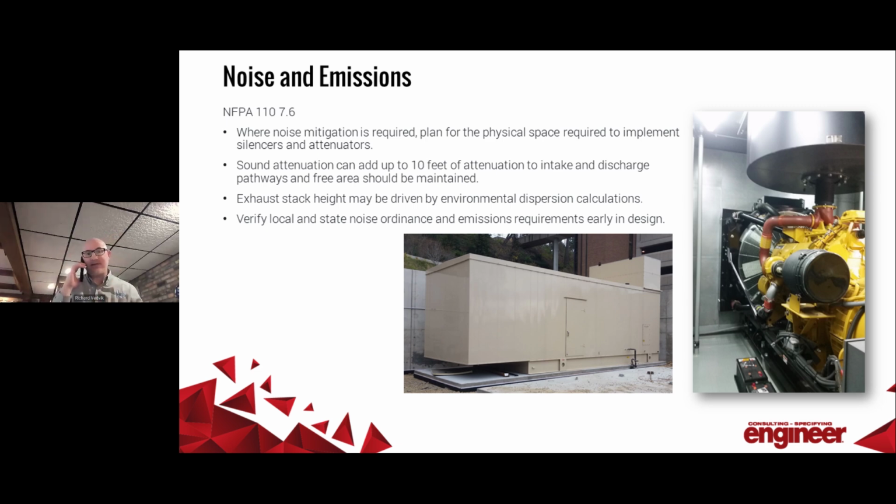Now, Tom mentioned noise, and noise is something I get a lot into. Obviously, your intake and discharge louvers for your radiator fan are going to take up physical space and cost money. It's not uncommon to see an extra $100,000 in enclosure costs and an extra 20 feet in enclosure length simply to make it quiet enough to comply with the noise ordinance.